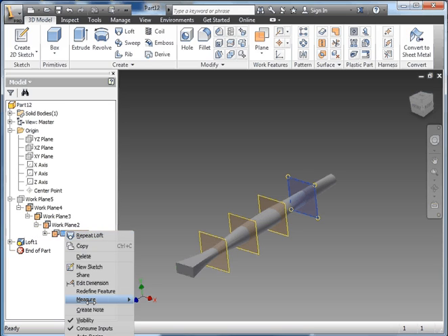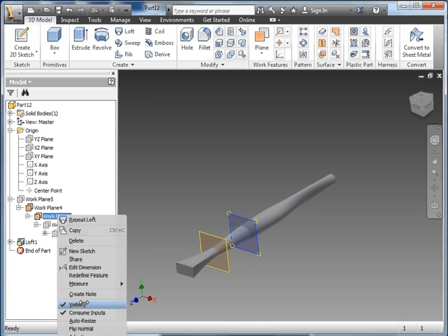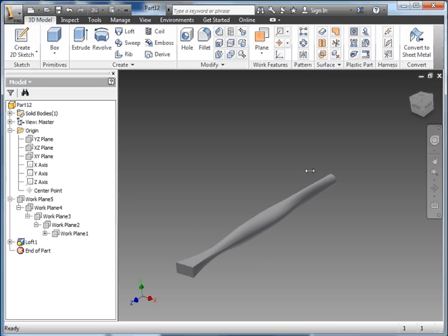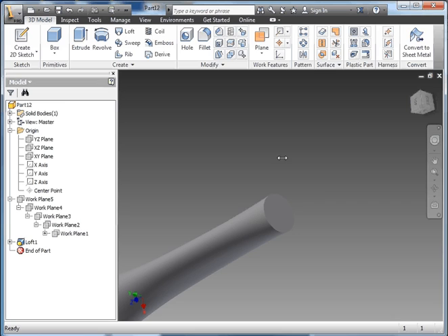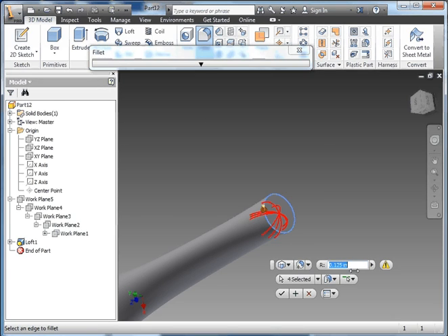Now, square-ended toothbrush, we could add a fillet onto that just to clean it up a bit. There's our fillet. This is a bit big, so let's bump it down to 1/16 of an inch and see what happens. 0.0625. Looks like that's going to work. So a nice rounded end. And now for the very end of the toothbrush.